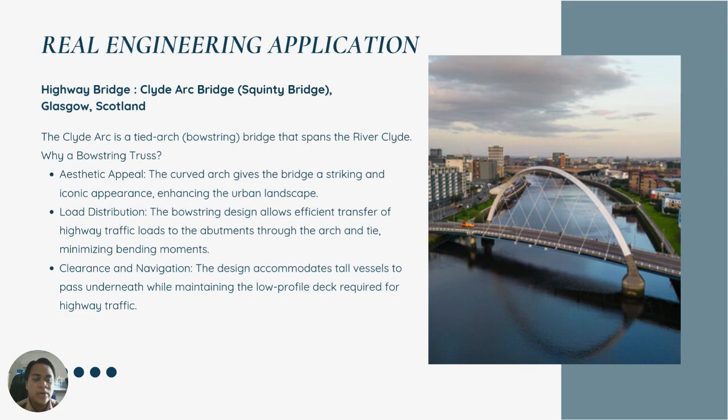Second, load distribution. The bowstring design allows efficient transfer of highway traffic load to the abutments through the arc and tie, minimizing bending moment. Last, clearance and navigation. The design allows tall vessels to pass underneath while maintaining the low profile deck required for highway traffic.